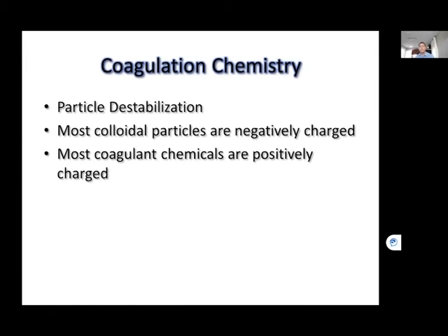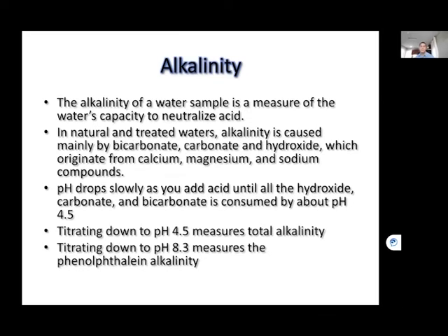Coagulation chemistry, particle destabilization. Most colloidal particles are negatively charged. Most coagulant chemicals are positively charged. So essentially, when you have your colloidal particles in the raw water, when it's untreated, they want to repel each other. And typically, the coagulant that you will use is positively charged, and it will attract those negatively charged particles and form floc, which then will settle in the sedimentation process.